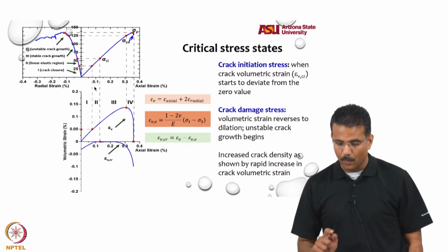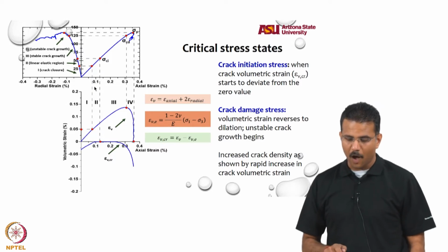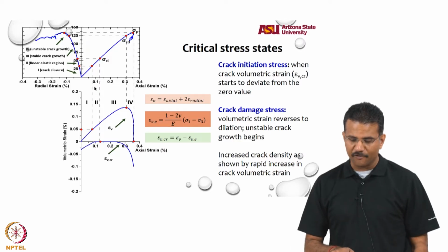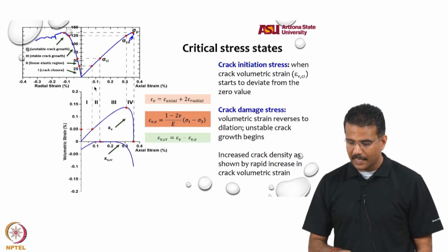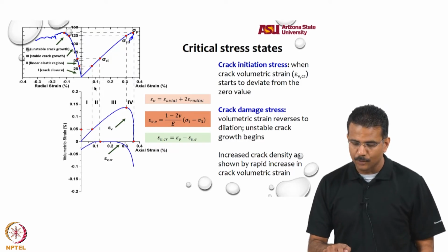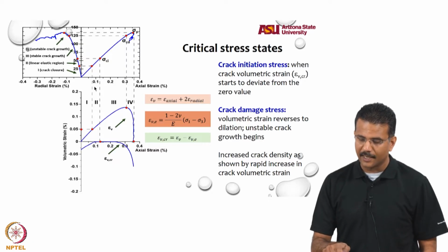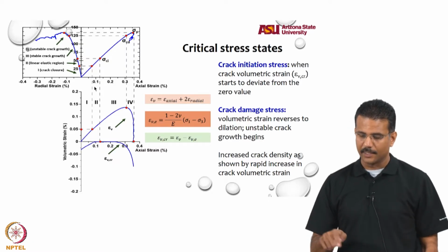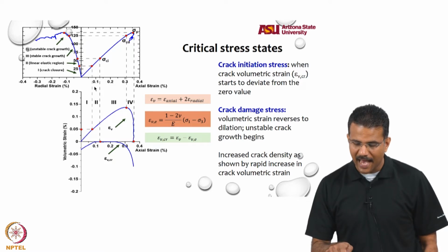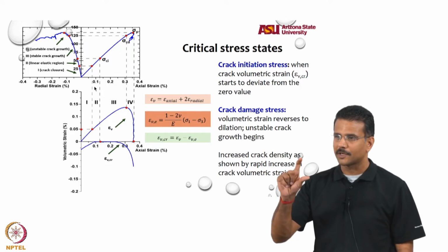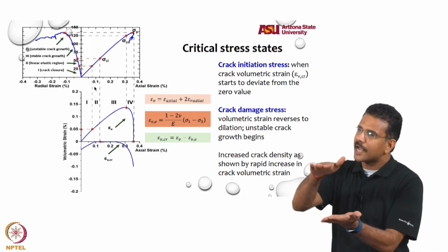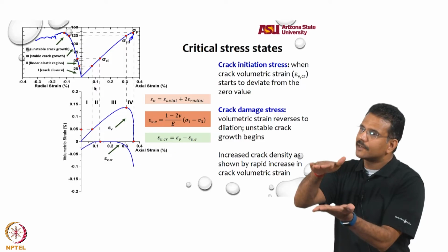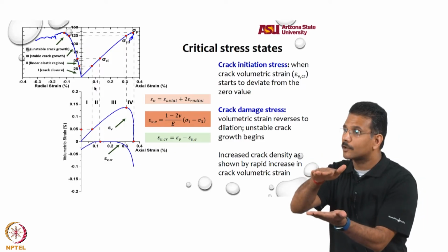Now if I take the point of volumetric strain of 0.05, 5% volumetric strain, and come to the volumetric strain curve, go up, hit the curve on the elastic part, that pretty much is the first part, about 25 megapascal, around that range, where you are compressing and getting increased stress because you are closing all the micro cracks within the specimen.